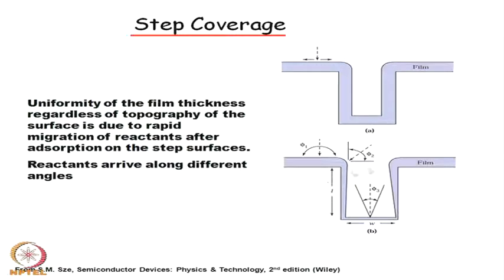Now, why is this kind of step coverage obtained for different processes? Actually, step coverage will be conformal if rapid migration of the reactants takes place after adsorption on the step surface.